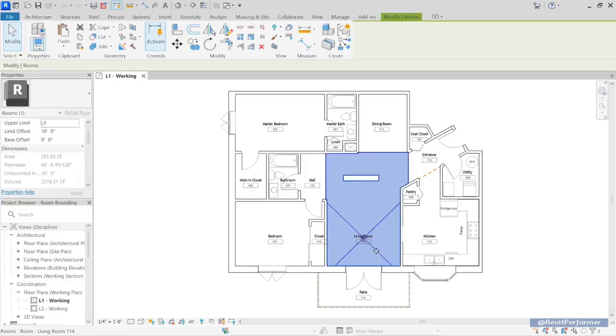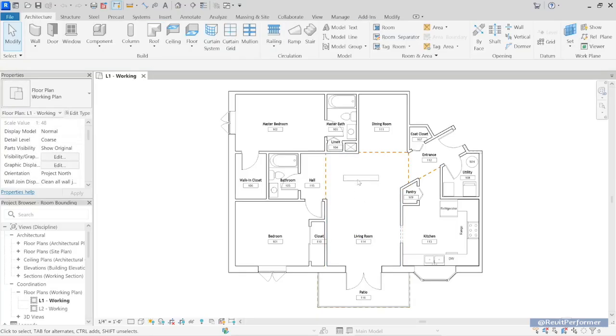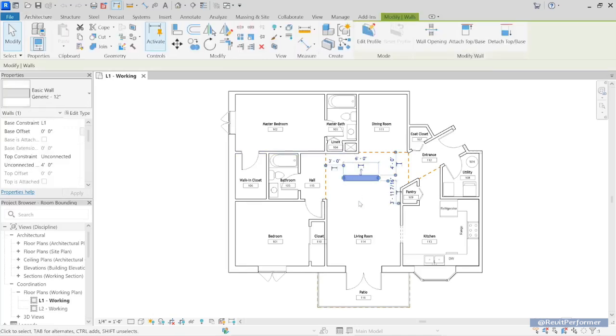that's what allowed us to shape the living room, as an example, to a custom shape, even though there weren't walls in those locations. So that's another example of room bounding. Well, there are times when an element that is room bounding by default, you would prefer not to be room bounding. So for example, there's this little low height wall that's right here that's maybe dividing this space into two. And maybe I don't want that wall to influence the shape or the size of the room.